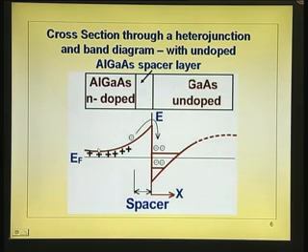Now you can see the energy band diagram, flat, a depletion layer coming up, and these are the donors, and this is a notch, and from this edge right up to this edge there is a depletion layer.